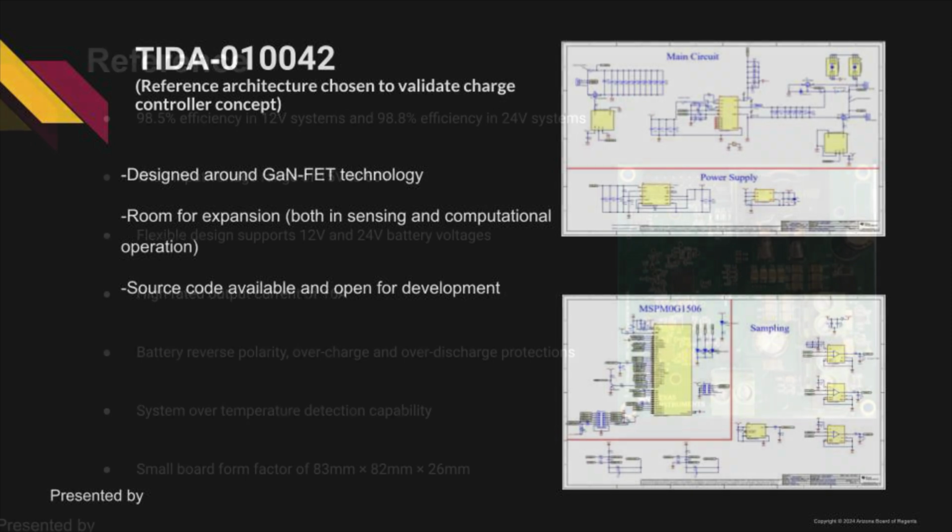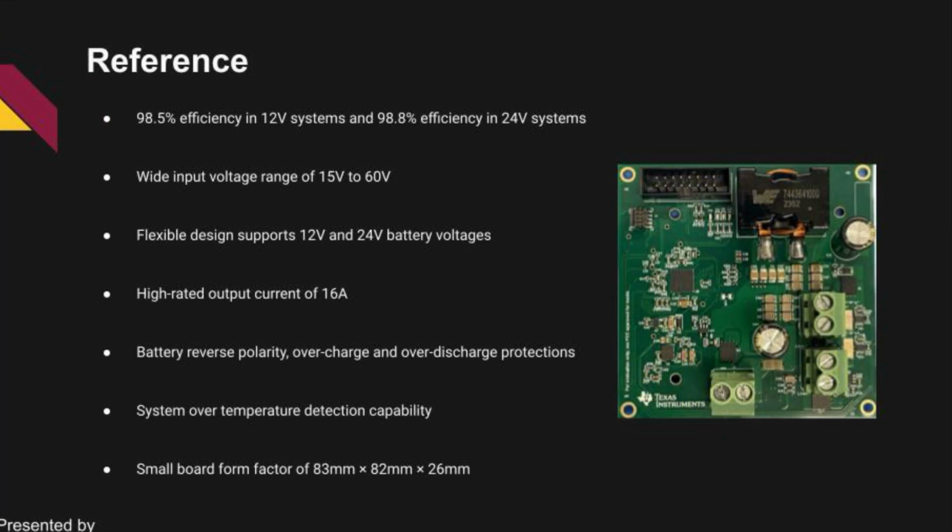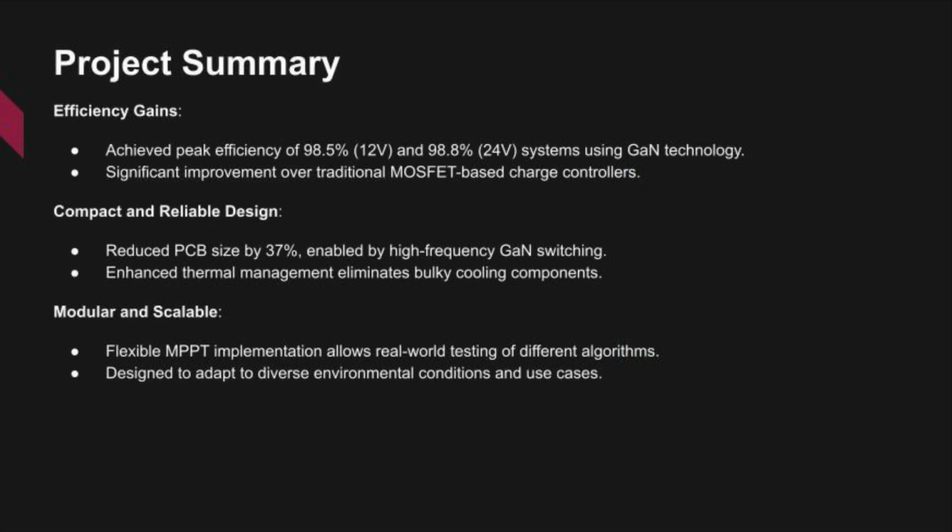While the reference design already included many of our must-haves as far as charger functionality, it was necessary to fully understand its workings in order to blend our additional inputs and firmware updates with the existing functionality. The modular MPPT charge controller achieves high efficiency charging with a reduced footprint and decreased material cost versus traditional MOSFET charge controllers. Both of these significant value adds are facilitated by the decrease in peak power through many of the components, provided by the increased switching speed.